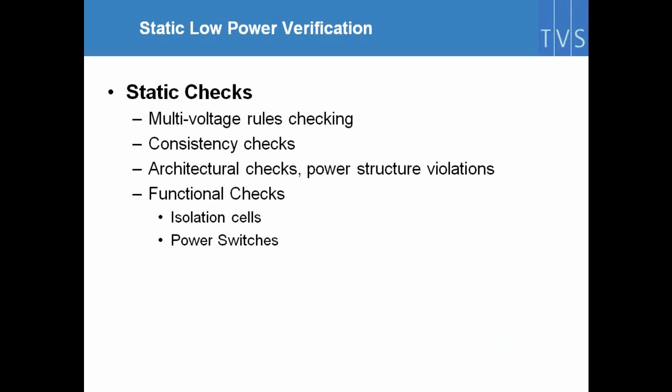For the static checks, this is the kind of thing that the tools provide. You can check structural checks for multi-voltage, consistency, architectural checks. There are also some structural functional checks, like for the isolations and power switches, which are done by the tool automatically.